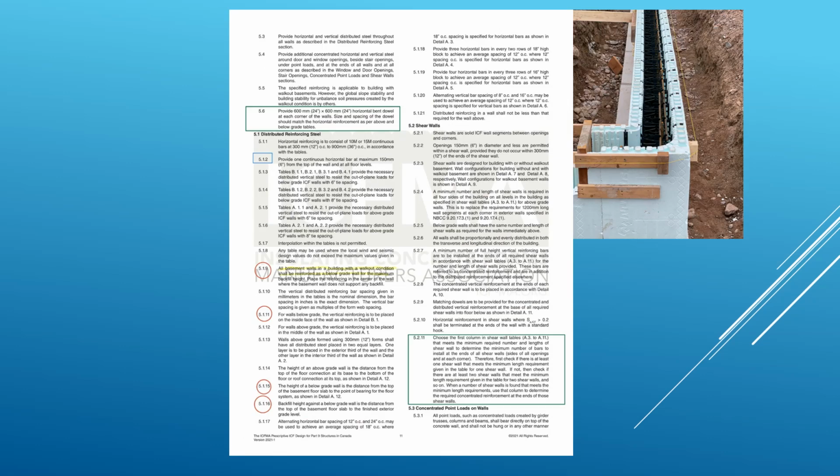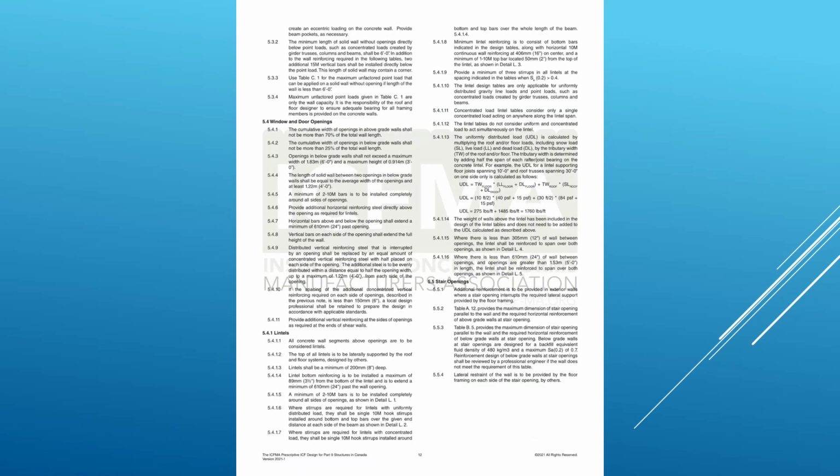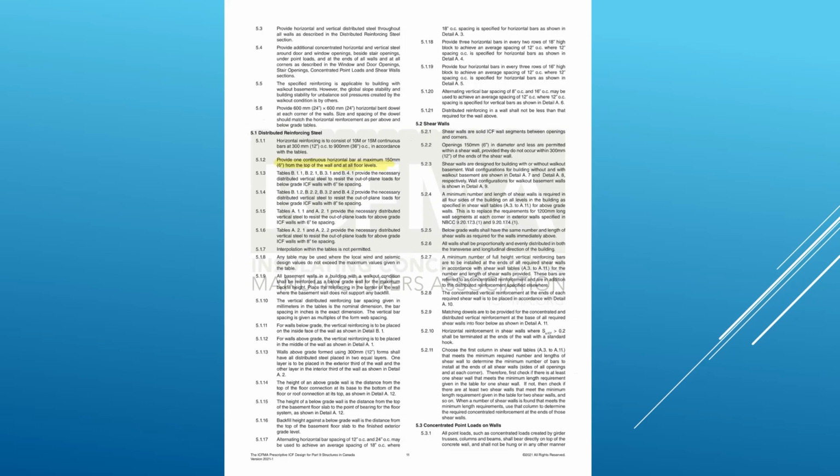Now, that was another one that I got stuck on, because I knew from previous constructions there's always a bent bar that goes in here and bends around. But I couldn't find it until it was located in the notes. So the notes will tell you where your bent bars are. I won't go through each one of these. I've got some of them highlighted, and we'll go through those in the next section when we're talking about holes in the walls. Window and door openings, same lintels, it's all there. You just need to go through it, highlight it, and understand it.